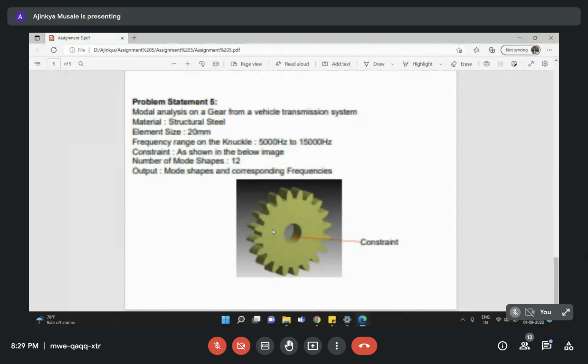And you know the formula very well. If you have some component and it is rotating, then it is creating some vibrations, right? So you can simply calculate the frequency from the rotating speed, and you can calculate the frequency of the gear by using the modal calculation, and you can check whether my motor frequency and the frequency of the gear are matching, or whether there is some difference between them.